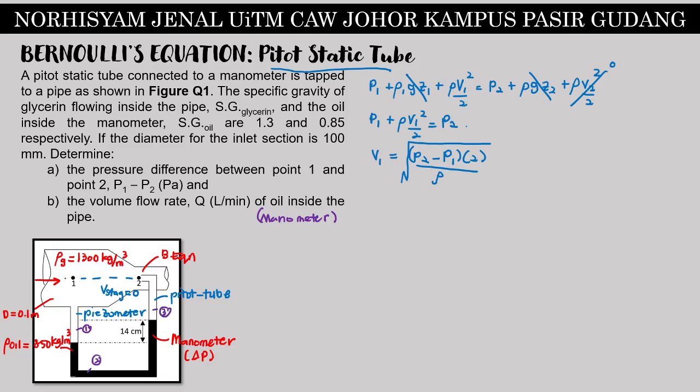The distance from 1 over here to this point is unavailable, but we can just put it as A or X or Y. It's just there in order for us to do the equation. And then you can discover that after that we can cancel out because of the same liquid here and here. So we do the calculation for manometer. P2 equals to P1, and then remember because this is higher and this is lower, we are going from left to right.